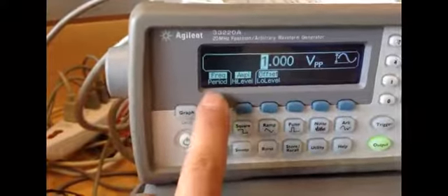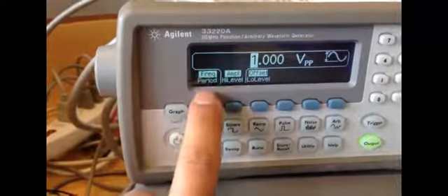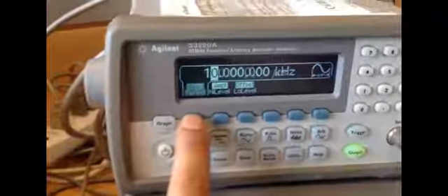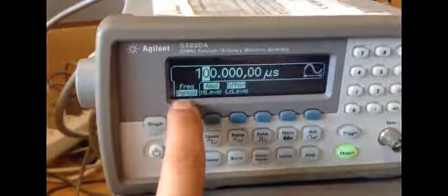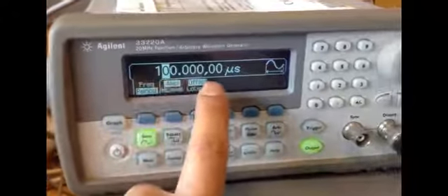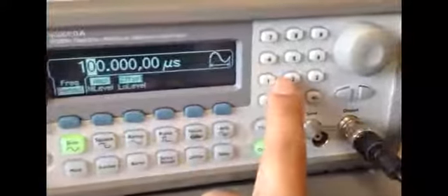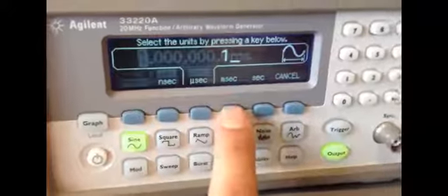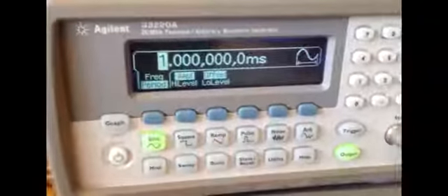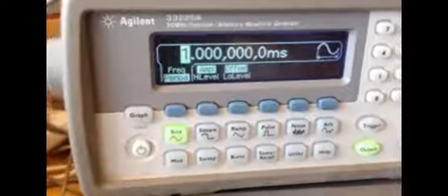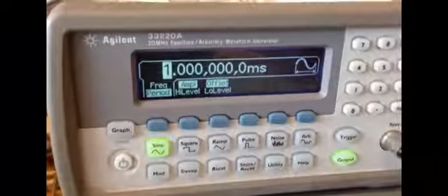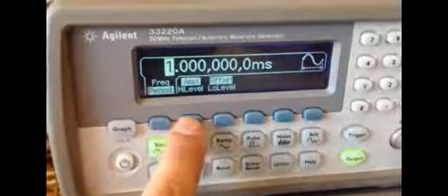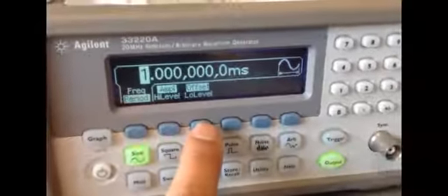For each button on the top there are 2 parameters, frequency or period. So if I click once on the button, it is going to switch to period, so you can set the period rather than the frequency. So let's say I want to set it to 1, and then it's going to ask microsecond, millisecond, so I can set to milliseconds. So now a sinusoidal signal with the period of 1 millisecond is going to be sent to the output.